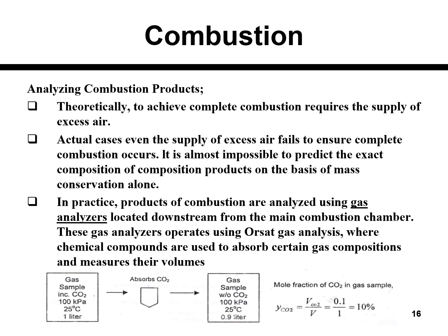So in practice, we usually use a gas analyzer, located downstream of the combustion chamber or in the exhaust pipe, and we measure the amount of product being produced. So we do the reverse combustion analysis, and then we calculate the amount of the required chemical combustion.